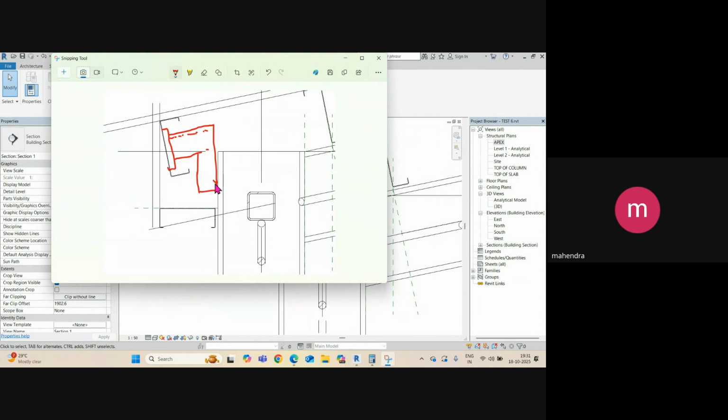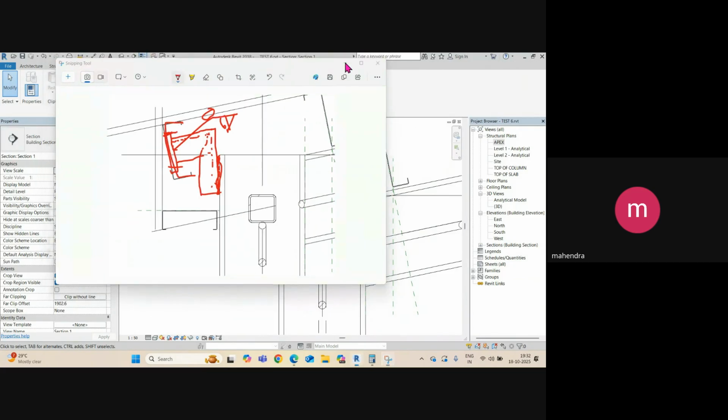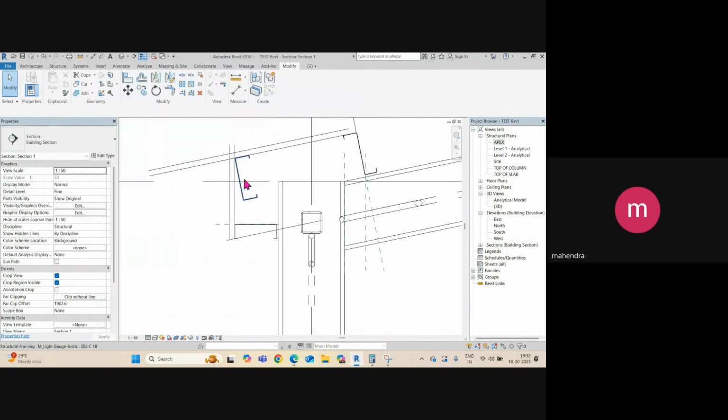This member comes with this column by welding here, and then this plate is welded to this member, all around, with a 6 mm weld. Then you add 2 screws or bolts, and then you can hold this member. So this type of connection we need to add. Those members we do not model here; we can cover them in our 2D drawings.